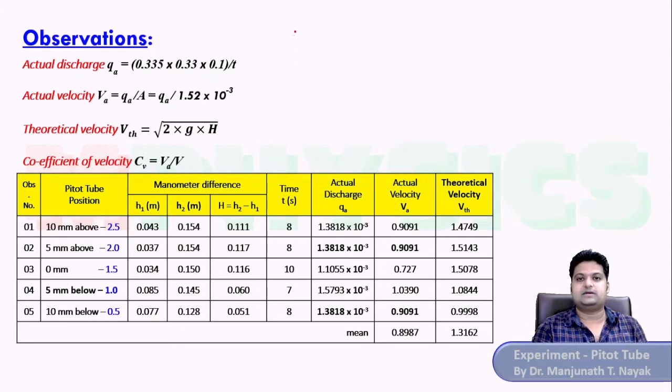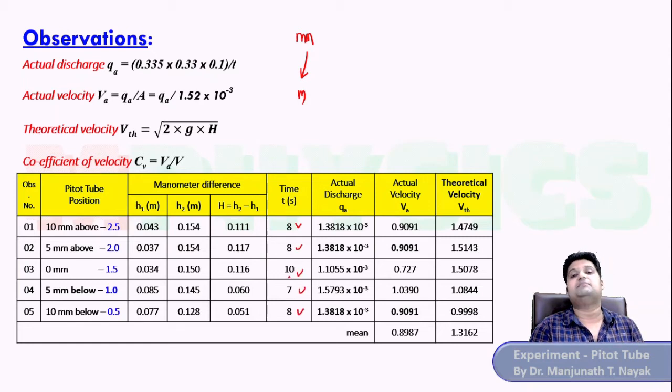When we measured it using the manometer, we got it in terms of mm. Now we have converted it into meters, and that's why you can see these extra zeros here. And of course, this is the other reading of the height too. Moving on, we just subtract the two readings and you will get the difference of the height in meters. And these were the times that we had calculated for the rise of 10 centimeters in the measuring tank.